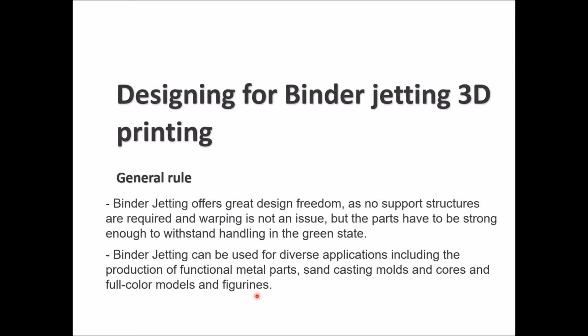As a general rule for this kind of technology, binder jetting can give you good design freedom because you don't need any support structures, and warping is not an issue for this method. But the parts will need to be strong enough to withstand handling in the green state, because they will be weak in the green state, so you need extra caution while doing post-processing until you're sure the part is not in the green state anymore. Binder jetting can be used for a lot of different applications, including production of functional metal parts, sand casting molds and cores, and full color models and figures for visualization.